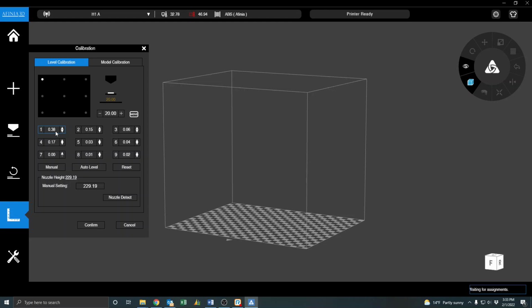What you'll see is you'll get warping if your area here is too wide, or if you try to accommodate for this wide area by raising the nozzle height, then you're going to have back pressure into your extruder, which will cause filament jam-ups. In a different video, we're going to go through how to get that set up so that everything is within this parameter. The closer to 0 you get, the better.